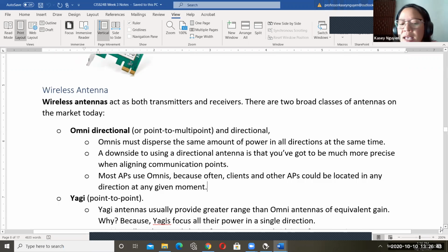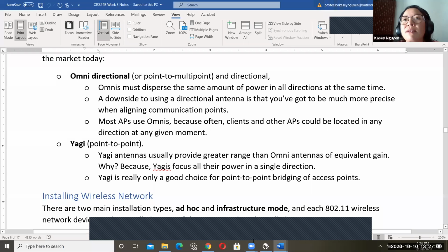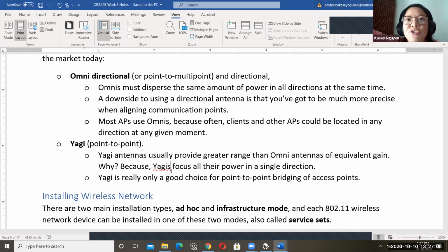With the Yagi, it's going to be point to point. They often use this type of antenna to connect an access point with another access point, directly to that next system. It was also used for television. Back in the day, people would have one attached to the roof.